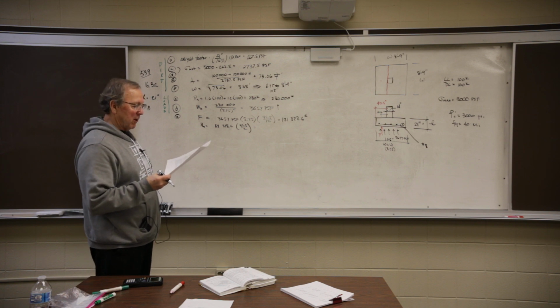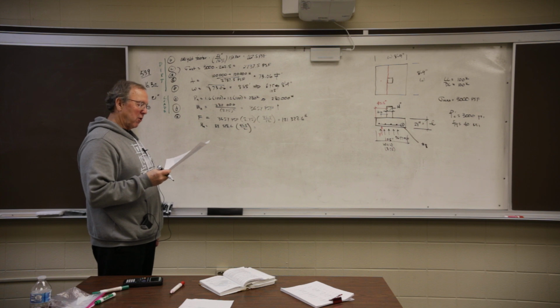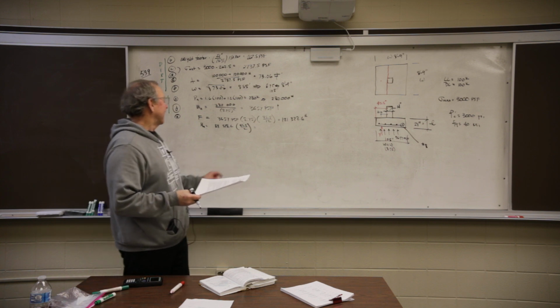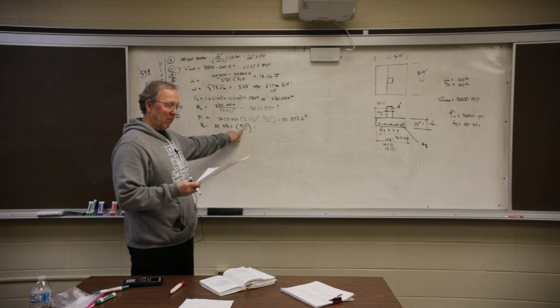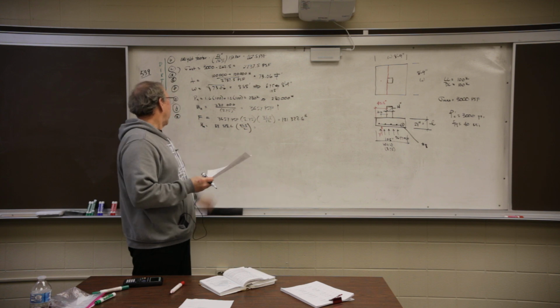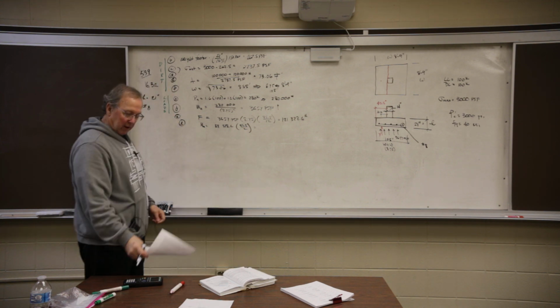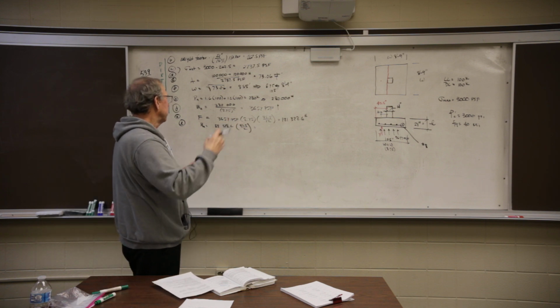If you look at the equation, Mu is F times (W minus WP) over 4. WP, of course, is the width of the pedestal. You should get this exact same answer, 22.75. Okay? So we're on letter L. I'm going to leave it in inches, so I'm going to end up with inch-pounds.